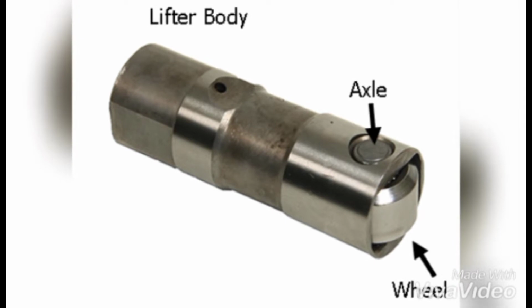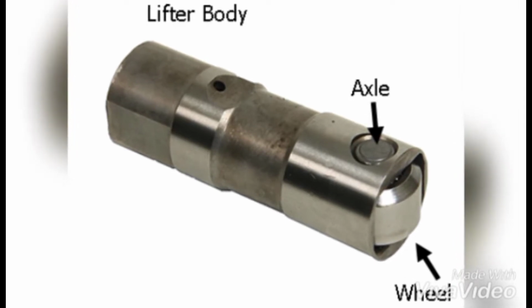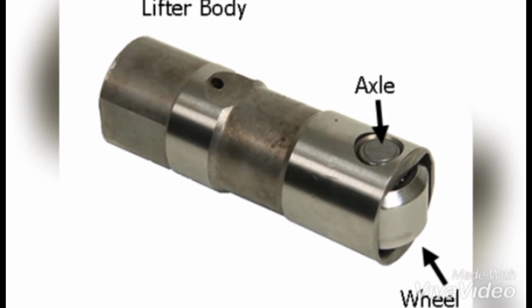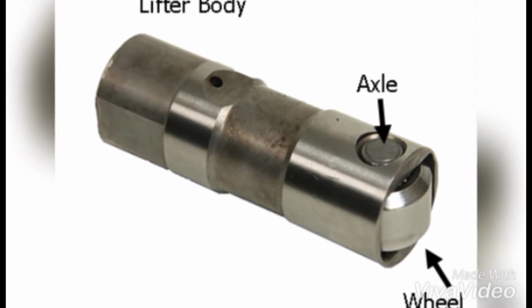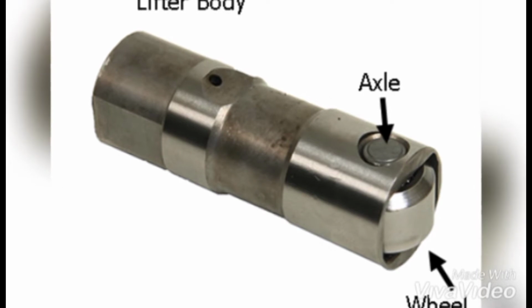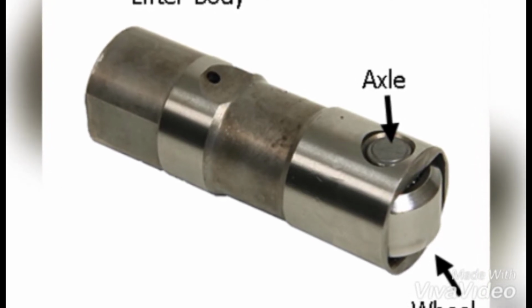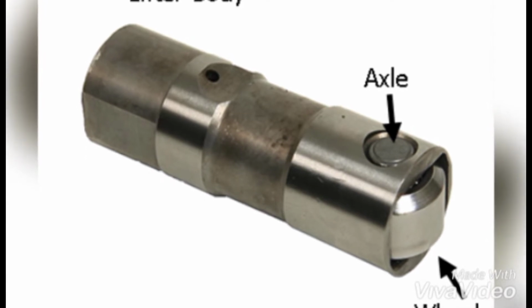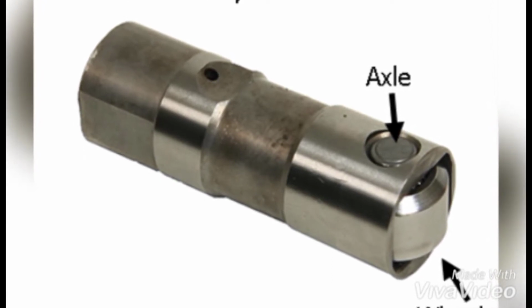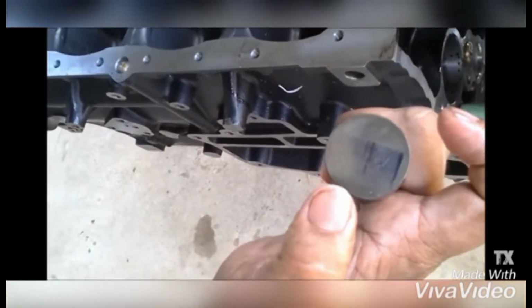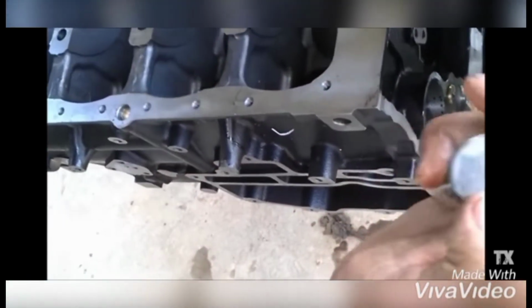Other than aerodynamics, we could also cite hydraulic valve lifters and roller tappets as a main reason. In the past, many engines and all high-performance engines employed solid lifters to transmit the motion of the camshaft through the rockers to the valve. This allowed more precise and quicker valve actuation, but they could not compensate for the expansion and contraction that occurs when an engine goes from a cold startup to normal operating temperature.